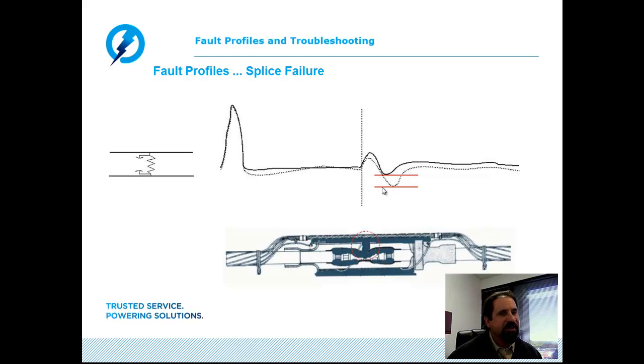That in essence tells me that during the high voltage discharging, I am changing conditions of that splice. I am lowering the impedance. I'm not getting it to where it's driving to a good hard solid arc, but it confirms to me that the breakdown is taking place in that splice. I can make a measurement to that location and then move my pinpointing equipment to that particular location for a more finite pinpoint.